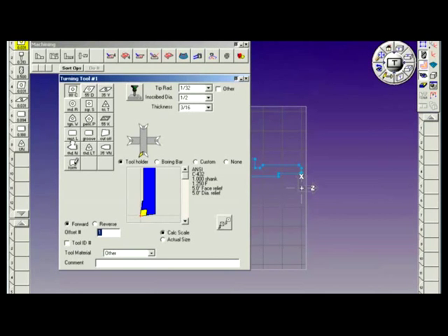We can also define rectangular, groove, cutoff tools. Threading tools are defined as a normal threading tool with the top-notch style, the cresting laydown style, and a 35 degree with a radius for specific threading. The form tool can be defined by drawing geometry at the origin of the part.